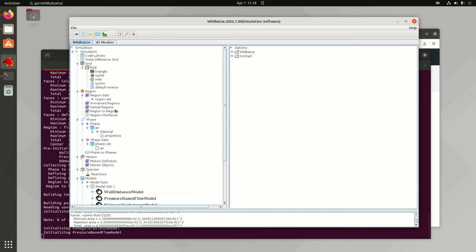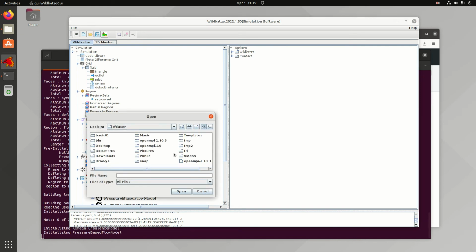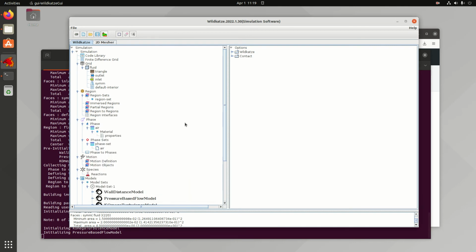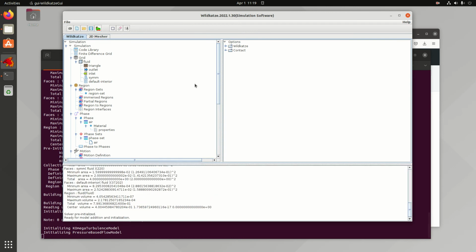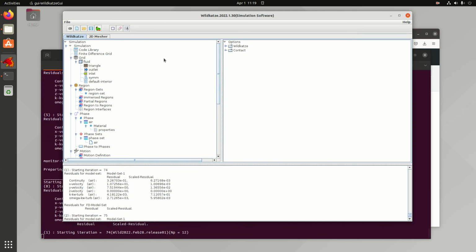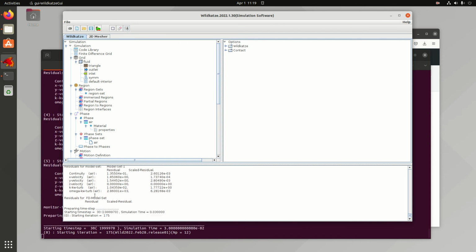The simulation tree we can save now. To save the simulation tree, obviously we will use this save button, and we go to this folder, and I save it as a try.stree. The extension is stree, that is simulation tree, and we saved it. While we can run the simulation from console, we can also run the simulation at the GUI, and this is done by, after initialization, this button to iterate, and if I press here, I can see that it's doing some iterations.